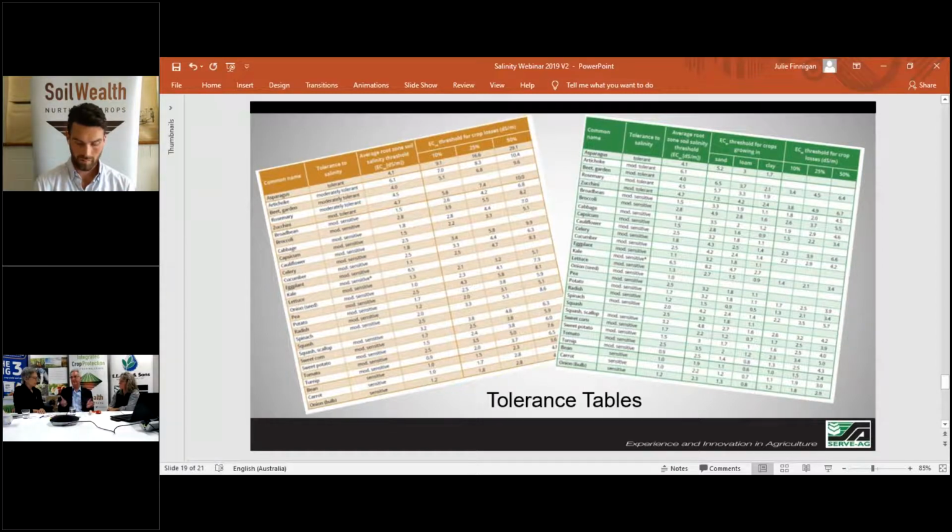Often indicative, particularly where you've got sprinkler irrigation or pivots and that sort of thing, where the watering may not be completely even, indicative of the influence of the amount of water that's being applied as well, and how quickly the soil's drying out and concentrating the salts back around the root zone. So the drainage is, apart from good irrigation management, probably vital. Yes, those two things together, the irrigation quantity and quality and the drainage, they're crucial to being able to put the water on and also to deal with getting rid of the salt problem.